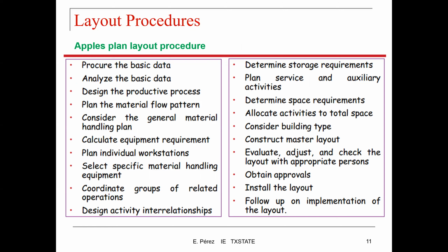Apple's plant layout procedure: these are the steps that they follow to procure the basic data, analyze the basic data, design the productive process, plan the material flow pattern, consider general material handling plan, calculate equipment requirements, plan individual workstations, select specific material handling